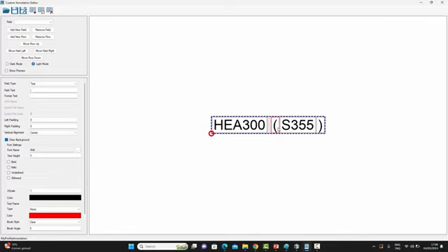I mentioned those while I was explaining user-defined attributes, that whatever user-defined attributes you create can then be used as parts of annotations as well. The third thing which you can put in a custom annotation is just pure hard-coded text. So sometimes, for example, you have brackets or some other things which you want to write down. In that case, you will insert a text.